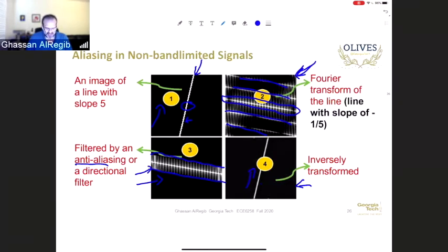However, the main reason is really the high frequency content usually is where the noise is happening. So you are just filtering out the noise, although you are sacrificing the quality and the smoothness and the sharpness in the image. But it's a common practice because of this.